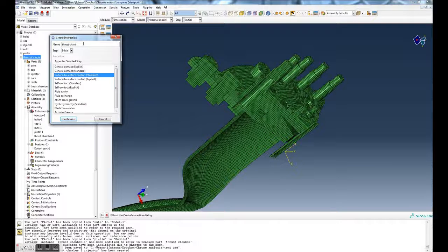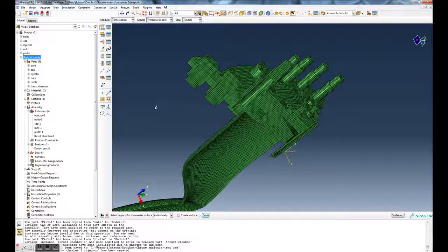And so forth, right? This last one, I won't talk too much about. It loops over the elements and plots each element using some MATLAB stuff and actually scales the deformation so you can see it a little bit. And that is pretty much it. That is the end of the program, okay? So the important stuff is this element looping, figuring out how you get the node numbers, the node coordinates, and this scatter vector. This is kind of important, okay?